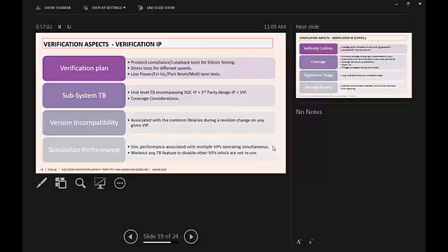The far-end loopback I'm talking about goes into the VIP and comes back, right? In silicon testing, you do both kinds of testing: one is the near-end and the other is the far-end loopback. For near-end loopback, the VIP is not required, and testing the hardware is not required, because it's just connecting the TX and RX lanes. The other thing is the far-end loopback.